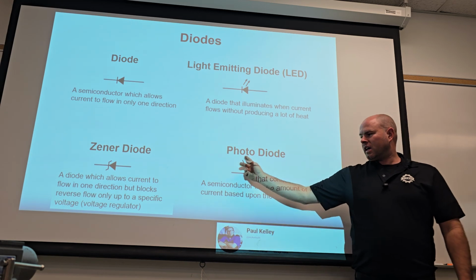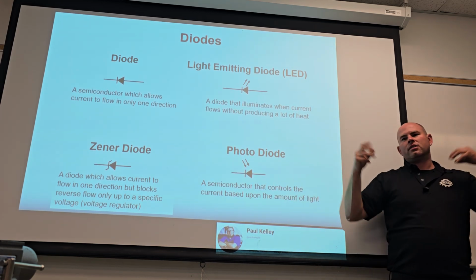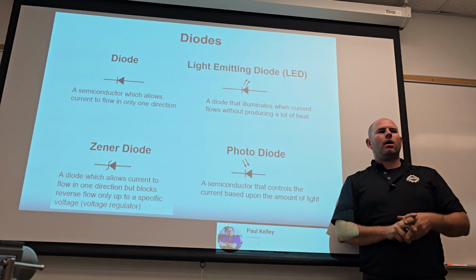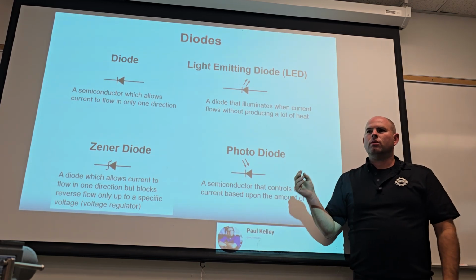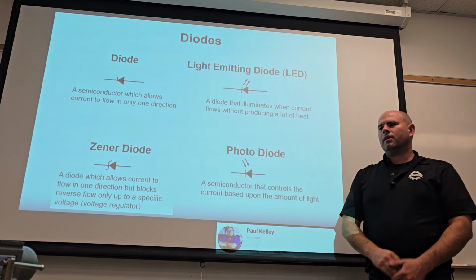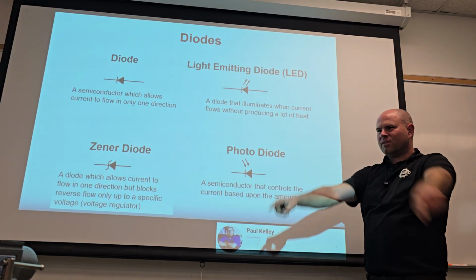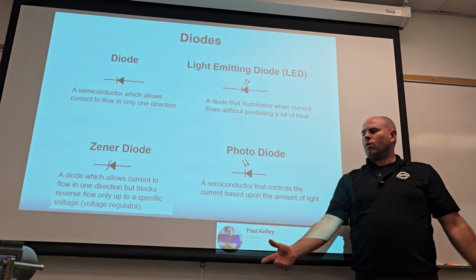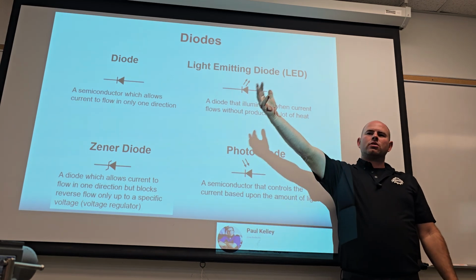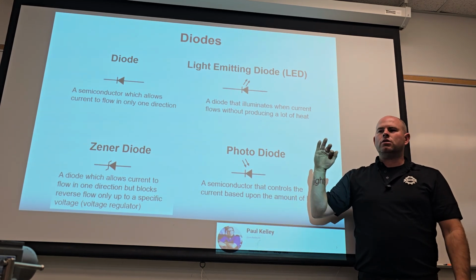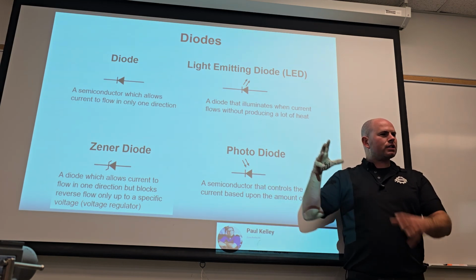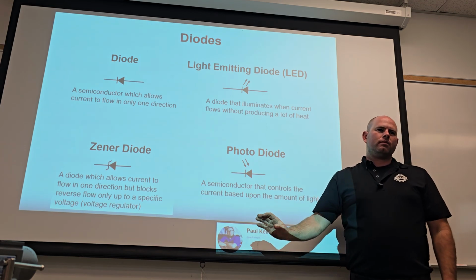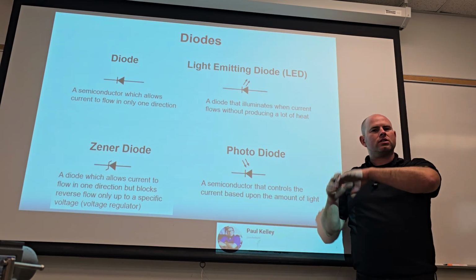So we can use this as more of a sensor to see if it's light outside. For example, when you have the automatic lights in the car, you put the headlight switch on auto and you just forget about it. Well, the photodiode is going to measure the ambient light coming through the windshield. It's usually in the form of a little dome on the dashboard. That's where the photodiode is, under there. And depending on the amount of light it gets, it'll tell the computer a number.